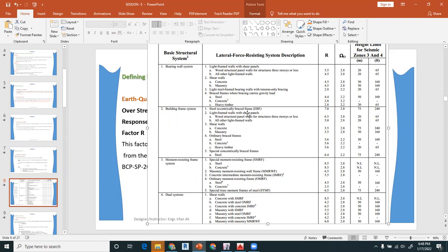For example, there is very small spacing of the ties and stirrups in the columns and beams, and you are keeping everything according to the code definition of SMRF. So we have to select the R value for concrete, 8.5. If you are not following any restricted values for the number of ties, the spacing of ties, the hook values, and the development length, or you do not want any special requirements in your structures, you can select IMRF or OMRF.